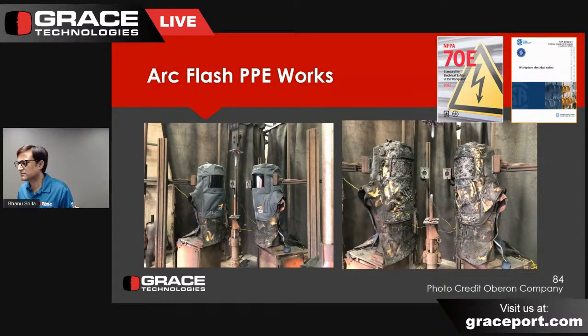You scrub that off, and in fact, this is what one of those looks like. So that's what it looks like after it's arc flashed. This is what it did. It took the heat for you instead of your face. It warped a little bit on the inside, but only enough heat would go through that for the onset of a secondary burn injury.